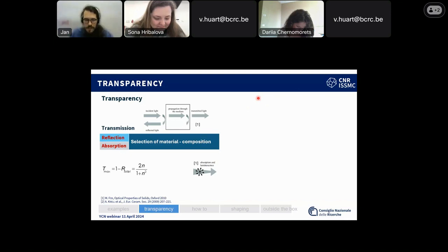So this gets a bit more complicated, because while yttrium aluminum garnet is happily sintered under vacuum, if you put the other one under vacuum, you have issues with gallium in a reducing atmosphere. And so you need to find a workaround, but ceramics give you quite a lot of possibilities to do that. A wonderful area it is.